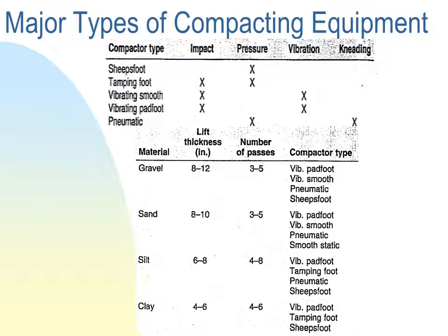And from that, we could understand that for each type of material, you have a certain family of compactors that is optimum to use. And from different experiments done, there is a certain range of lift thickness. And the word lift is the layer that you will be compacting.